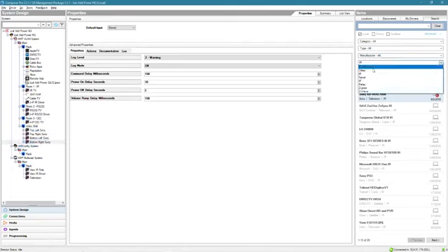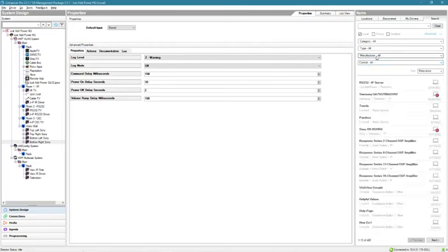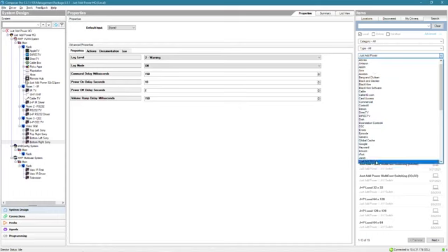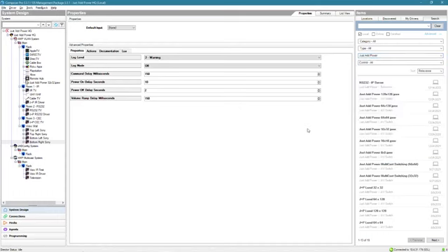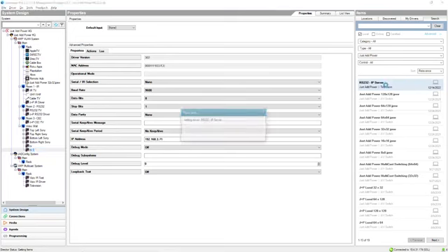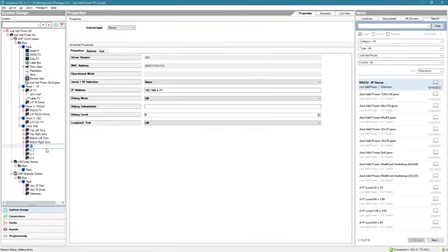The second thing we need to do is we need to get Just Add Power drivers, because what we're doing is we're controlling video wall layouts. And so we have to control the Just Add Power devices to do the zooming necessary to build our video wall. So we're going to need 4 RS-232 IP servers as well. 3, 4. We'll rename them as well.